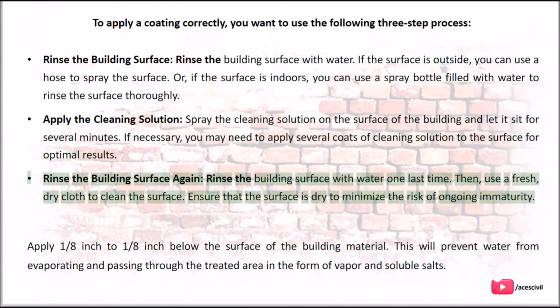Rinse the building surface again. Rinse the building surface with water one last time. Then, use a fresh, dry cloth to clean the surface. Ensure that the surface is dry to minimize the risk of ongoing efflorescence.